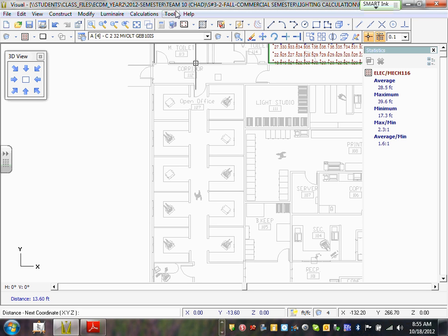Now, in order to use the simplified method, guys, the simple, easy visual method, you have to have the dimensions and the height of the building. What's the height of this area? Everything is 10, unless you know otherwise. So make sure you write on a piece of paper, the height is going to be 10, okay? You need these numbers to do this method. You need the width, the length and the height. The height is 10 already. Now I need the width.